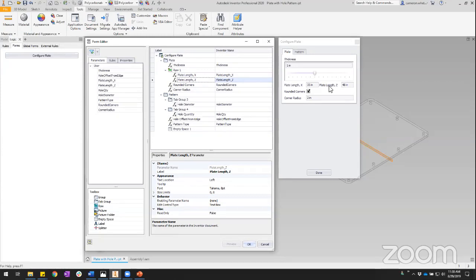So that's more what I want there. Another weird little quirk that you'll see is with the label spacing and how it controls horizontal spacing in the forms. How it works is for a given section, whether it's a tab or a group or just part of the form without a tab or group, whatever's in that section that has the longest label determines where the label field ends and the control field starts.